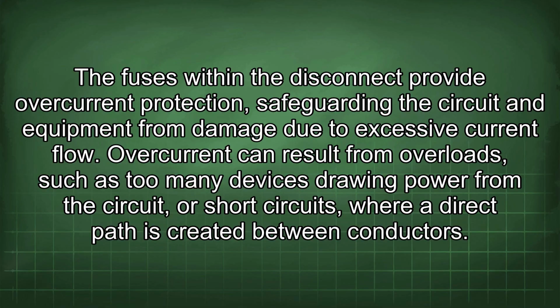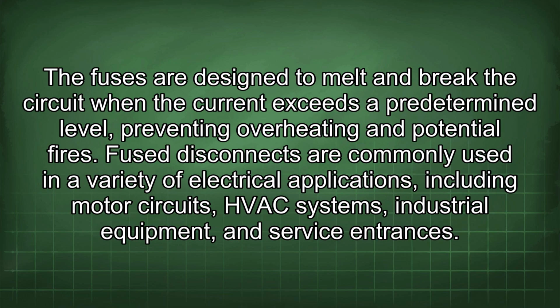Overcurrent can result from overloads, such as too many devices drawing power from the circuit, or short circuits, where a direct path is created between conductors. The fuses are designed to melt and break the circuit when the current exceeds a predetermined level, preventing overheating and potential fires. Fuse disconnects are commonly used in a variety of electrical applications, including motor circuits, HVAC systems, industrial equipment,